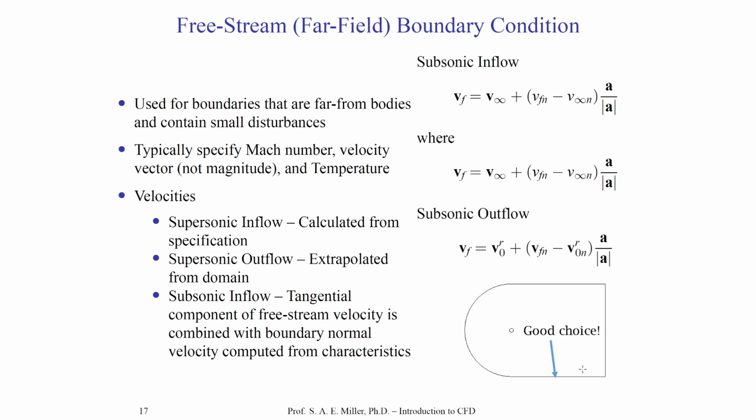The flow will seamlessly come in from the left if we set the flow to be, say, in the x direction with a particular velocity, and we'll go over the cylinder, which might be a no-slip or slip wall, and leave the domain behind the cylinder. You'll notice the distance from the cylinder to the exit of the domain might be 10 or 15 cylinder distances. That's very small. For excellent calculations, I would recommend 50 to 100 cylinder diameters downstream.